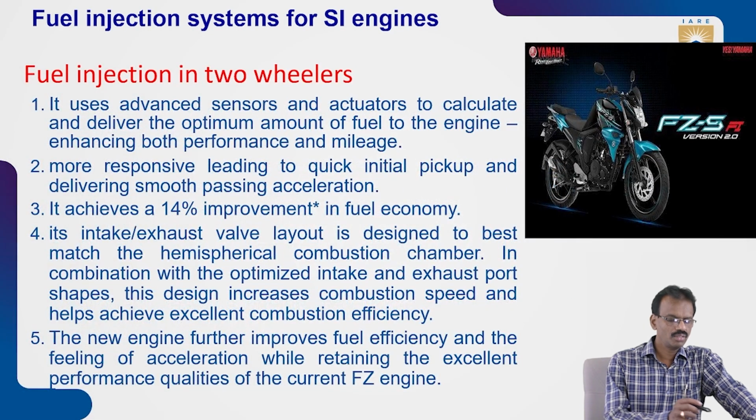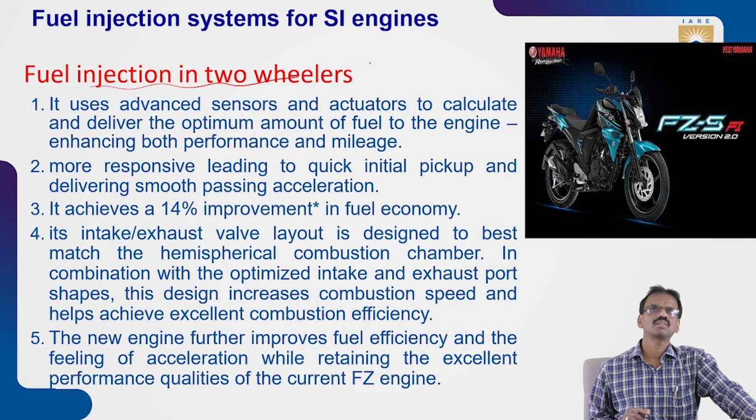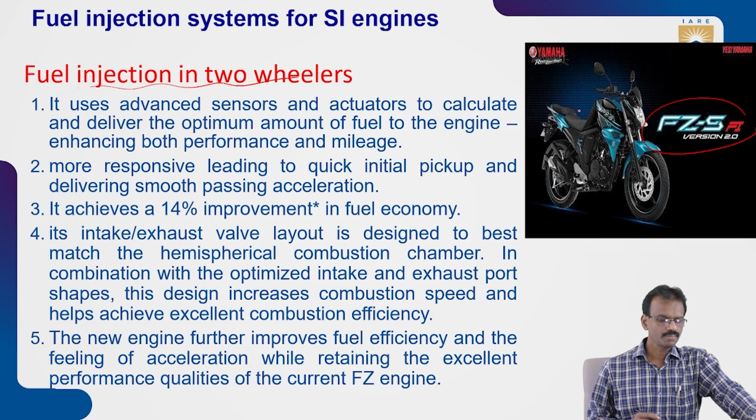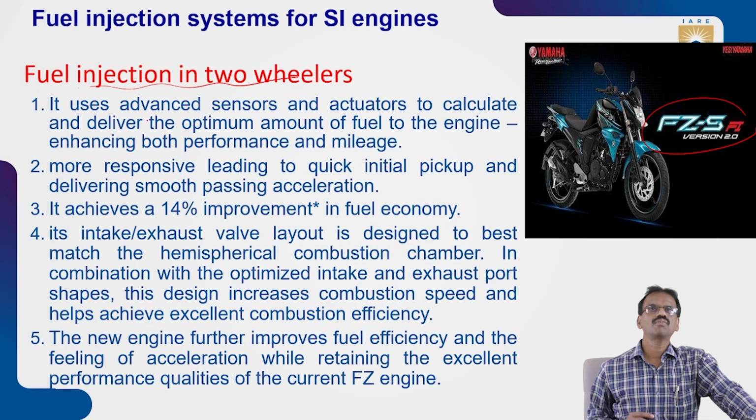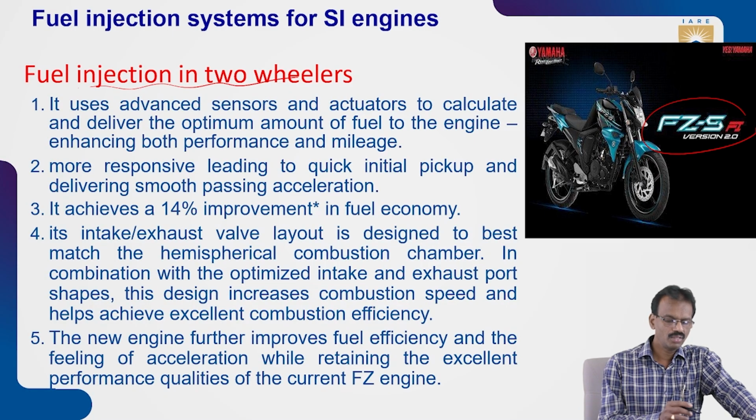So nowadays the fuel injection systems are used in two-wheelers, mainly FZ-S. It uses advanced sensors. You know that fuel injection systems are run by the ECM. The ECM takes the feed signals from the sensors, and based upon the sensor signals, it supplies the fuel, air fuel mixture.